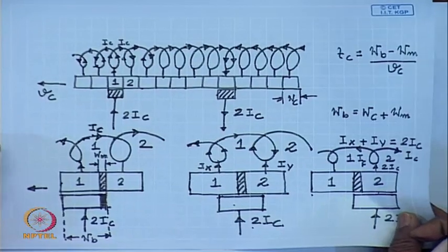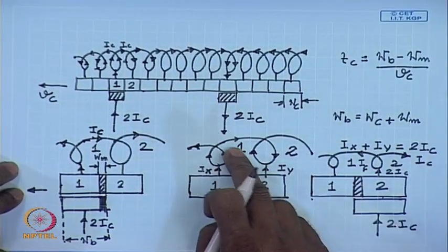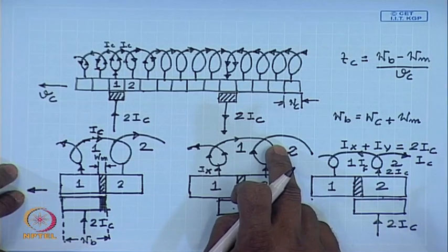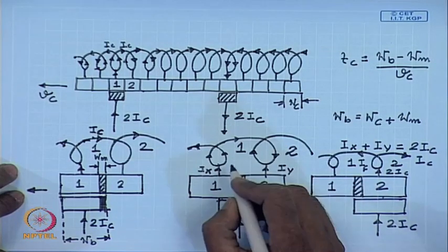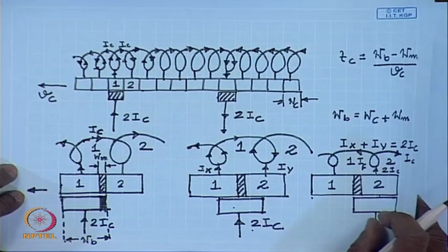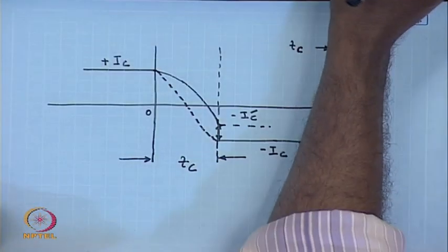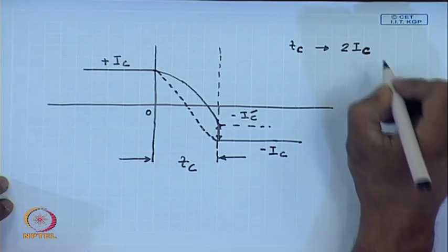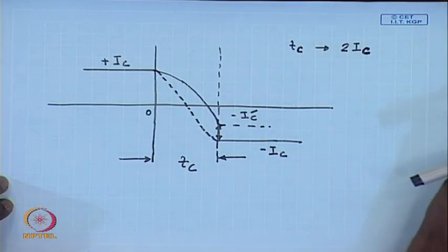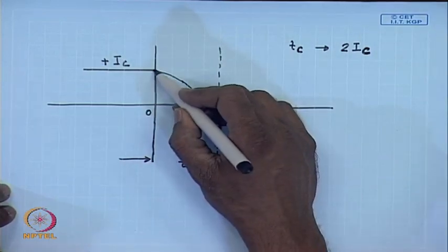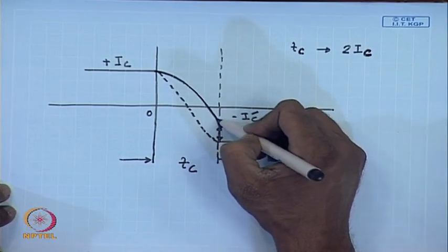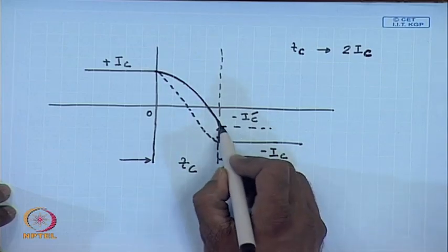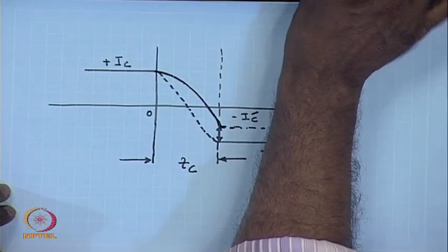Now, the coil undergoing commutation has some leakage inductance. This is mostly due to the overhang part of each coil. So, a coil will have a leakage inductance of Lc. So, this leakage inductance will delay the change in current in the coil undergoing commutation.